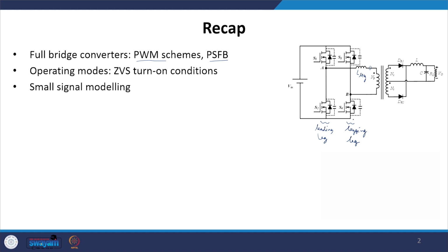Also, sometimes due to delay introduced in the gate driver circuit, the average voltage applied will be different, and that is when we will have different voltages applied across the transformer. When the diagonal switches are on, they are not equal and opposite, and that leads to some residual DC flux which keeps growing during operation of the converter.